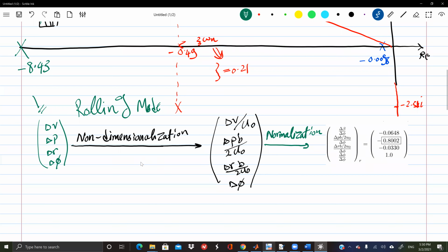Whereas if it's disturbed on a vertical bump or something, you will feel the oscillations. It takes a while. You feel it yourself. So the rolling mode, or the roll response of the airplane, is quite fast. It's not oscillatory, right? And all of this we get just from this analysis. We get the eigenvalue, get the corresponding eigenvector. We know we get a lot by this simple analysis.